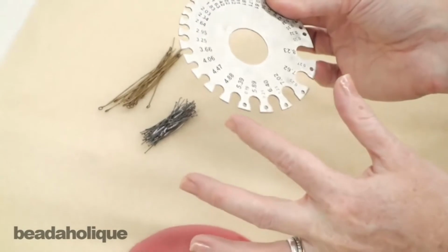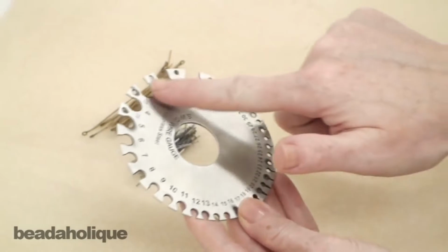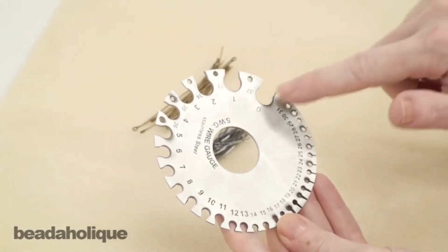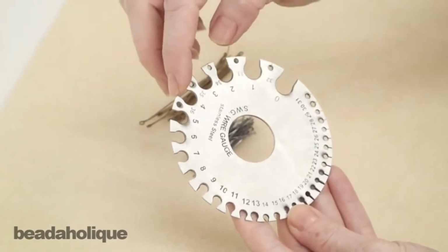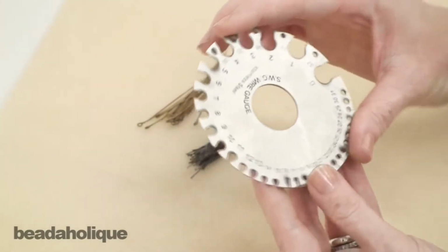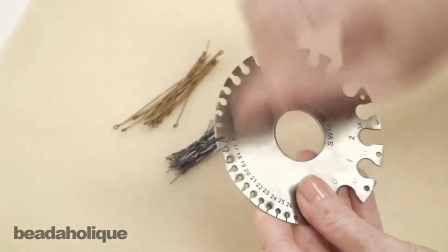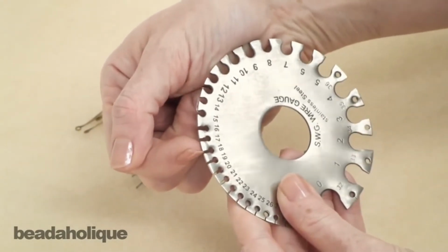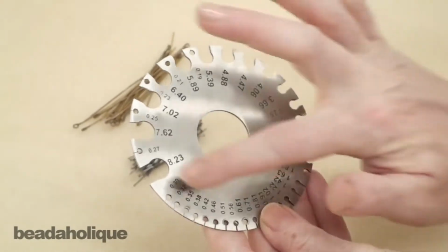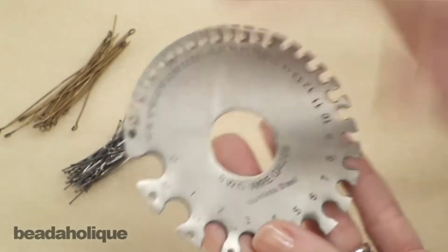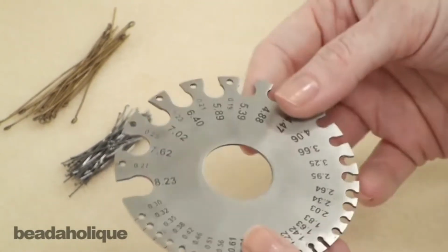Just because the corners can actually be quite sharp. So what you have here is this disc. Along the outside, it shows you the wire gauge, and it goes from 0 all the way up, and it keeps going around to 36. So it's going to show you gauges from 0 to 36. What you want is for the wire to fit within the slot. Don't worry about the little round spot down here. It's the slot right there that you want your wire to fit into. If you flip it over, you'll see it has its corresponding millimeters. As you can see, 32 gauge wire is actually 0.27 millimeters. So that's handy to know too.